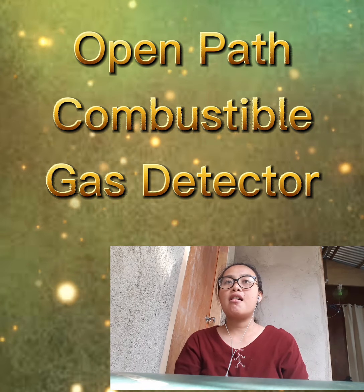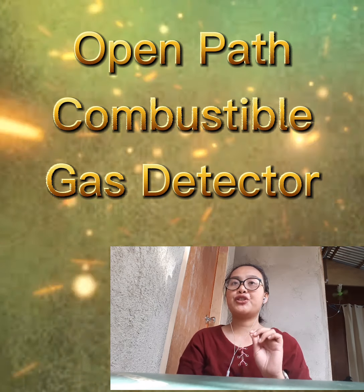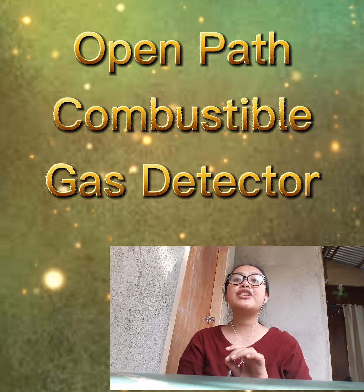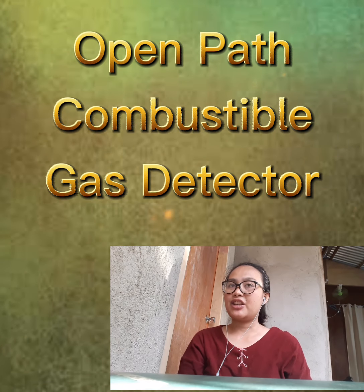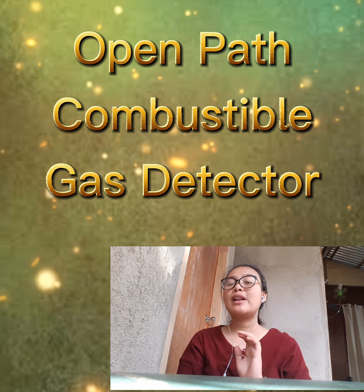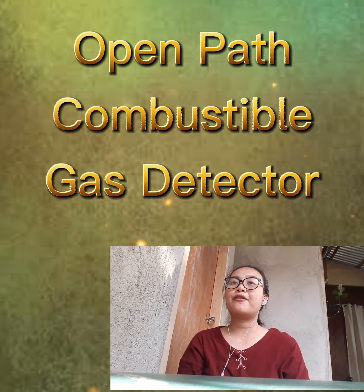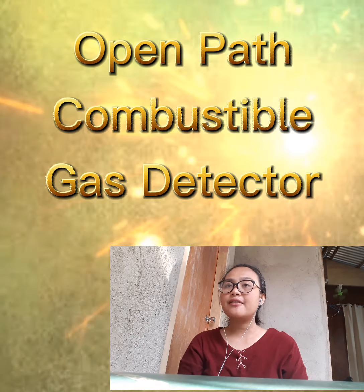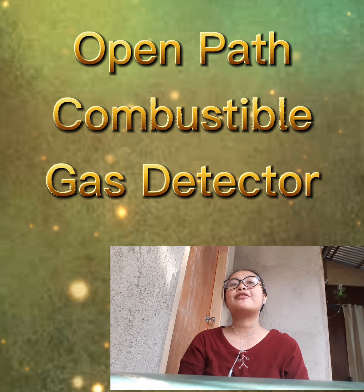Its criteria are: first, the transmitter and receiver shall be suitable for mounting on standard instrument posts. Second, it shall be provided with the means to ensure reliable operation without false alarms. And also, continuous optical checks for beam blockage shall be provided.